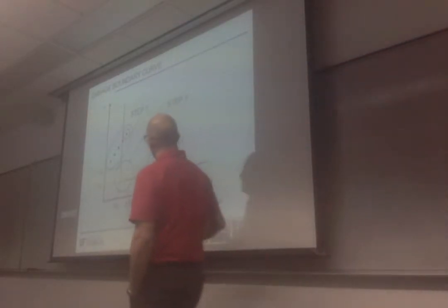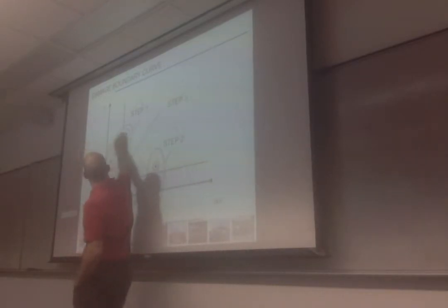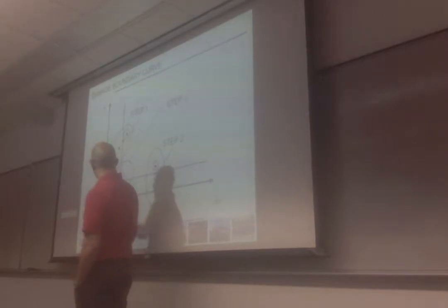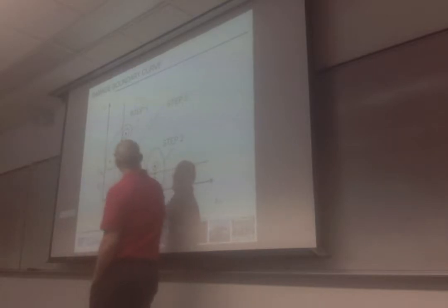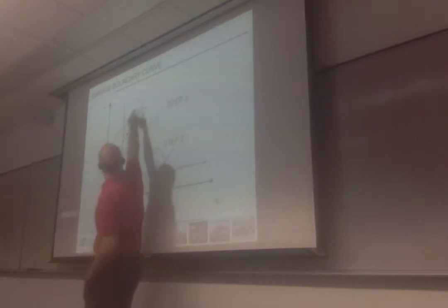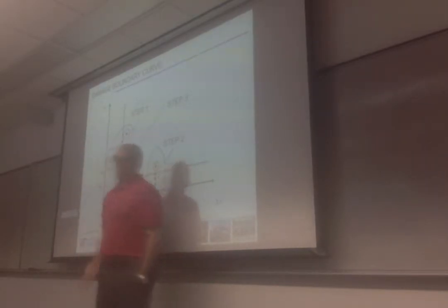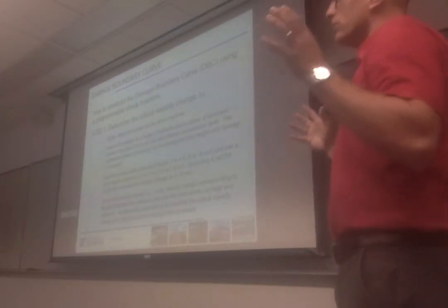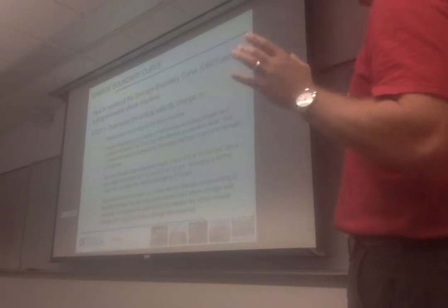So step 1 is to work on that vertical line here that illustrates, or find, the critical velocity change. To do that, as you will see, we'll use a half-sine type of impact, so we have to use multiple impacts. What you have to do is attach your product rigidly on the shock machine.